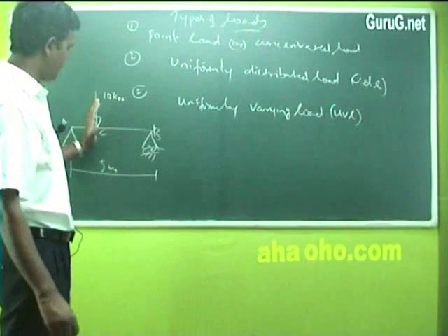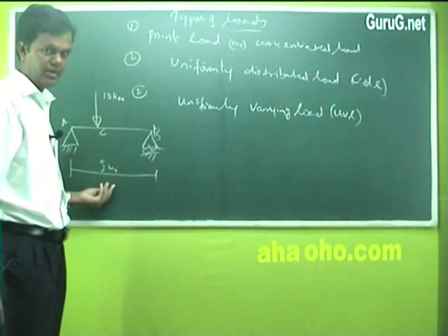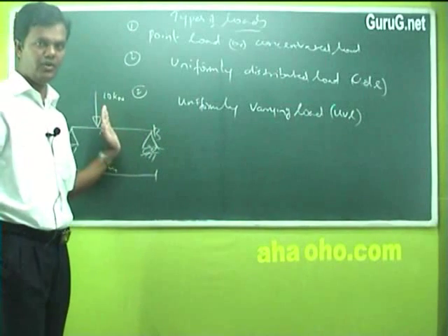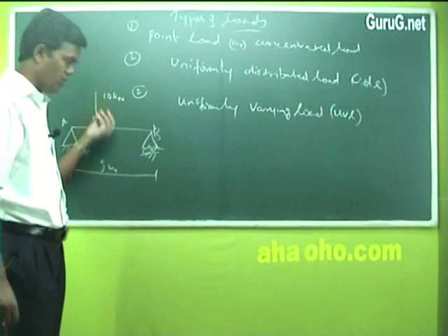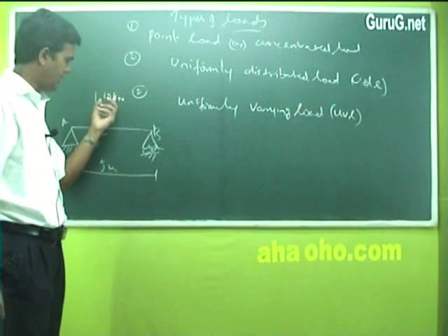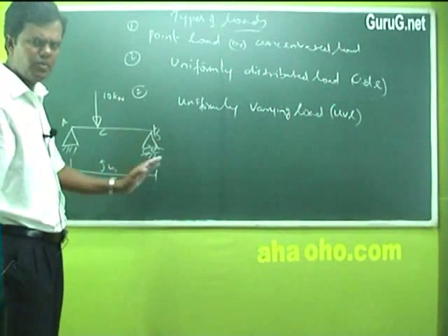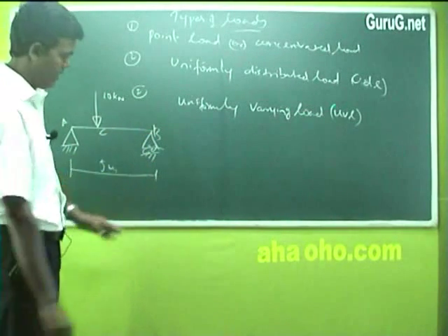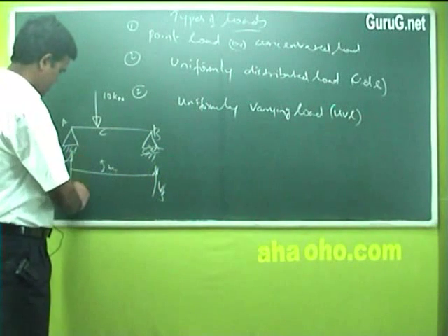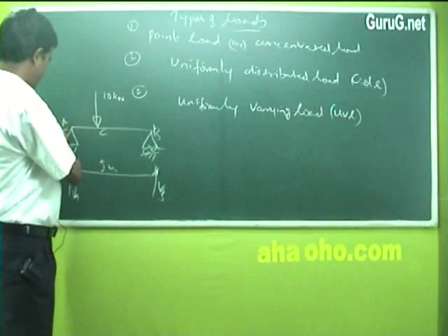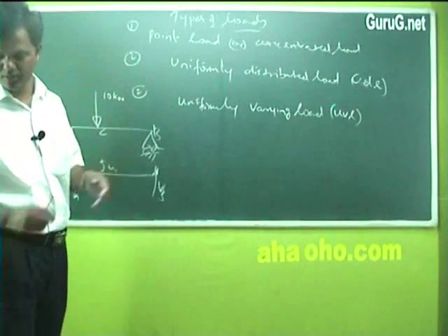Fine. So this we can take directly, and if it is a vertical load, since it's acting down, you can find out the value of sigma H or sigma V. Horizontal is not required here, it becomes 0. Vertical alone we need. Sigma V means acting down, it's minus 10 kilonewton. We'll find out the value for the reactions. Roller will have VB here, and the hinge will have VA and HA, the horizontal load. That's it. So this becomes your point load.